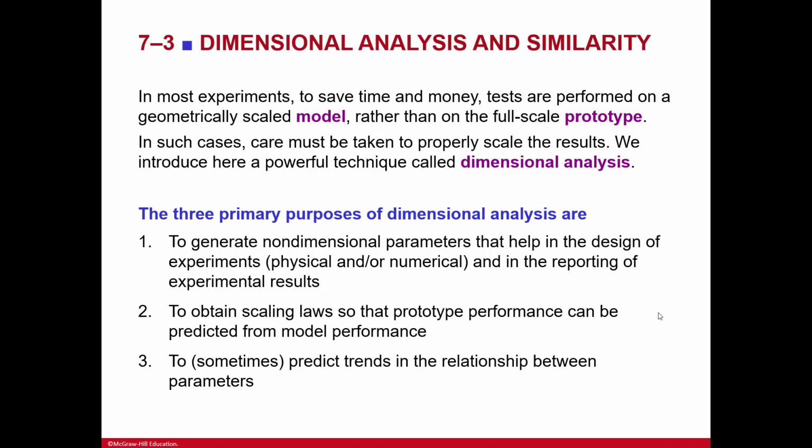So here, in such cases, care must be taken to properly scale the results. We introduce here a powerful technique called dimensional analysis. Here are three purposes: to generate non-dimensional parameters that help in the design of the experiment, to obtain scaling laws so that the prototype performance can be predicted from the model performance, and to sometimes predict the trends in the relationship between parameters. And so one here, or really all three, right?